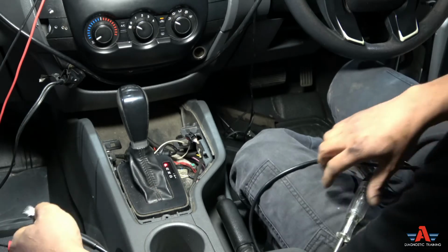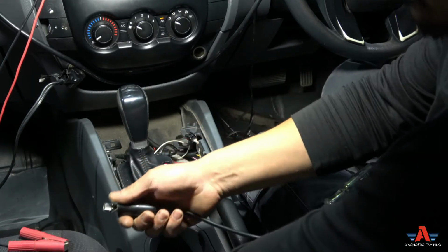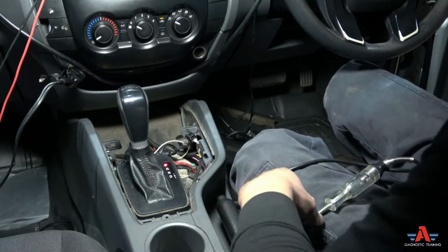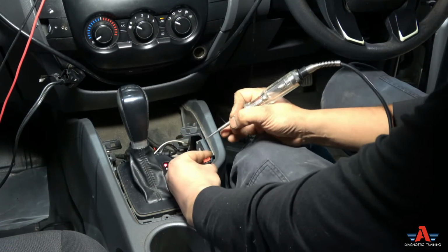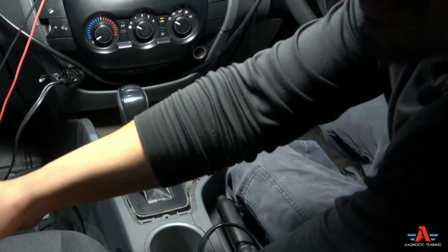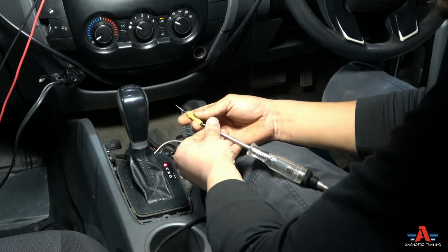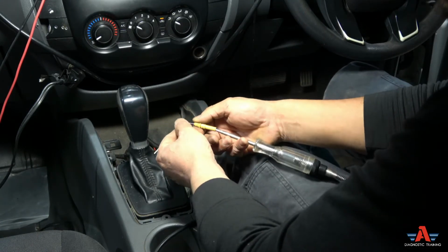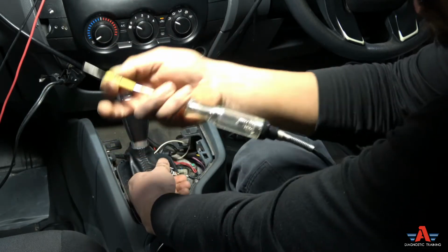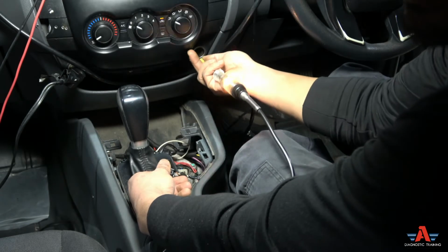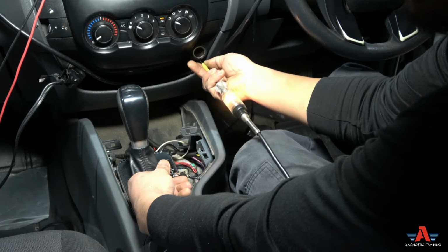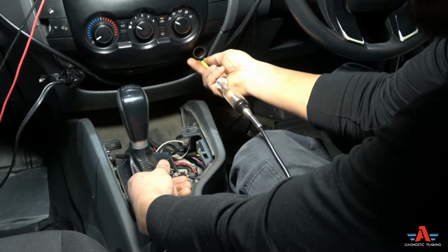Now let's see if there's any earth, any power, whatever we see. Turn the ignition on, right? So I'm just gonna go here, I might need to back probe it. I'm just gonna quickly put my probe on my end of the test light, connected to battery positive at this stage. Let's just verify our test light works. Okay, my test light is working. I'm just touching the cigarette lighter ground there, guys.